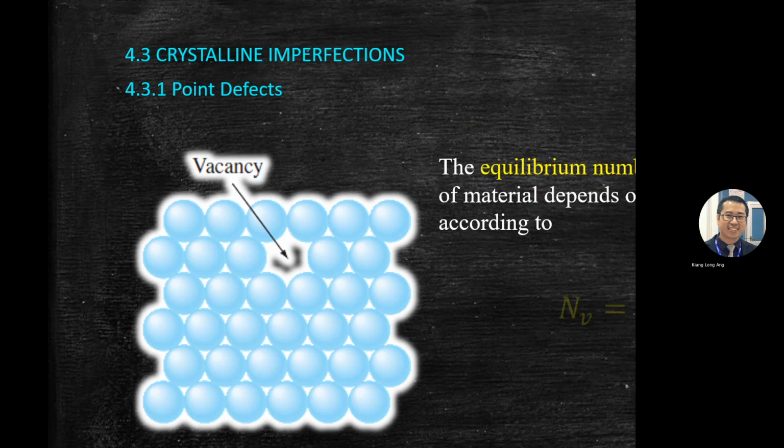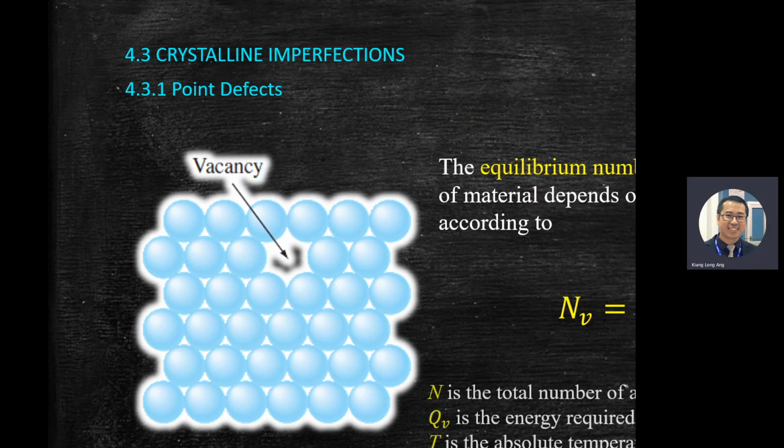Let's read. The first equation for today is called the equivalent number of vacancies. It means you find the number of spaces or missing atoms in the point defect category. N_V means vacancy, and exponential means e to the power of something, minus Q_V over kT.